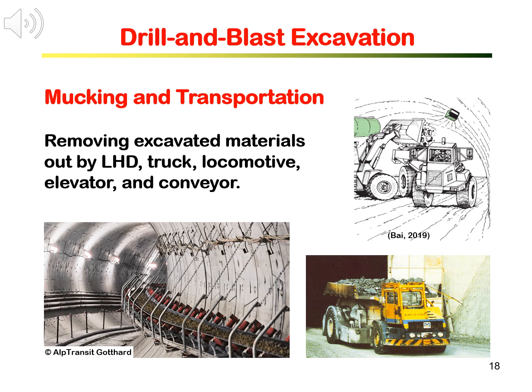For the Gotthard Tunnel in Switzerland, due to the concern of the local community, mucking was transported by a purposely built 3.2 kilometer long, 5 meter diameter mucking conveyor tunnel with a conveyor belt system 3.7 km long, transporting 6 million tons of rock debris to a neighboring valley, without trucks passing through the villages. The mucking conveyor tunnel with conveyor belt system is shown in the photo on left.